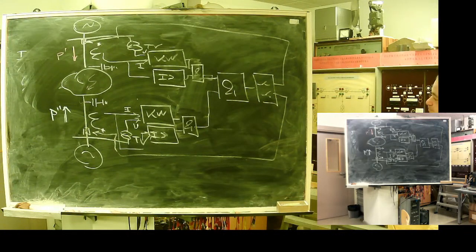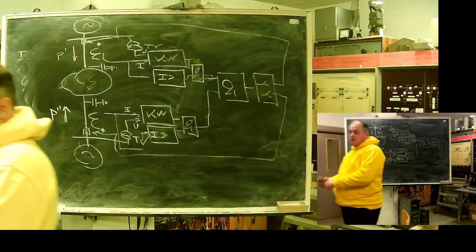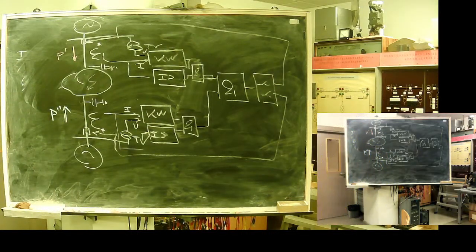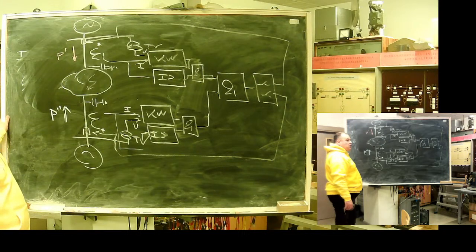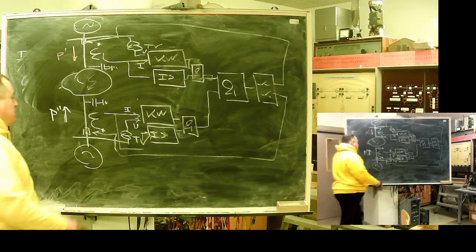The version based on power flow isn't reliable. It should be combined with something more. It can be fixed for a power line, but I strongly recommend not to use it for the protection of transformers or generators.